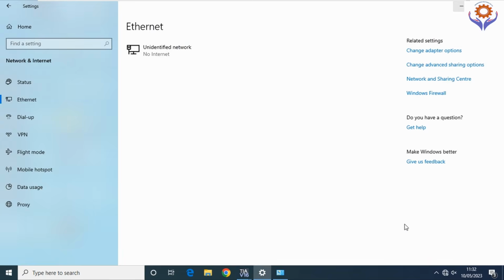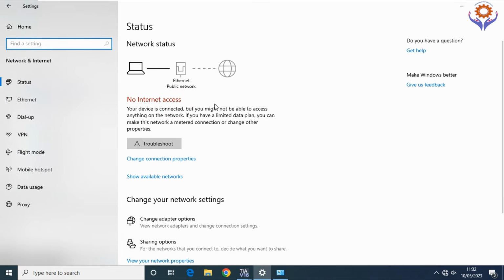Before connecting to the main PLC, I need to check the network configuration of my PLC, whether it is matching and whether it is pinging or not.